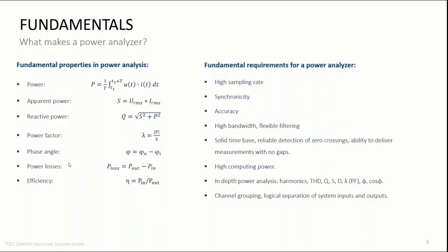Finally, when talking about systems and efficiency, a power analyzer must be able to allow a logical grouping of its input signals, to which the user can then apply specific settings like filters and consider them as separate entities on their system, for example, inputs and outputs of different stages. This makes the calculation of power losses and efficiency possible.